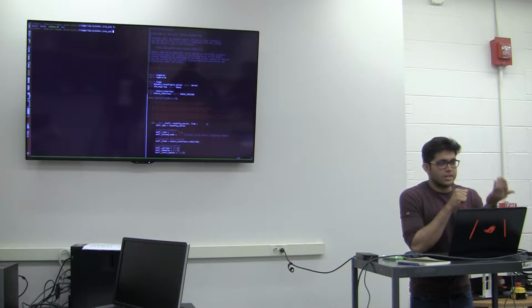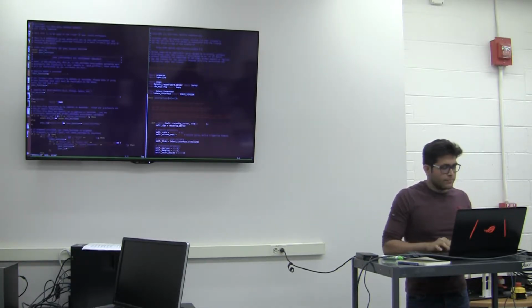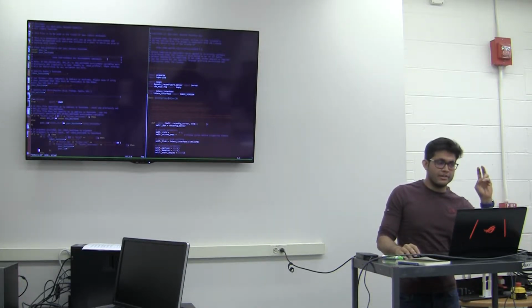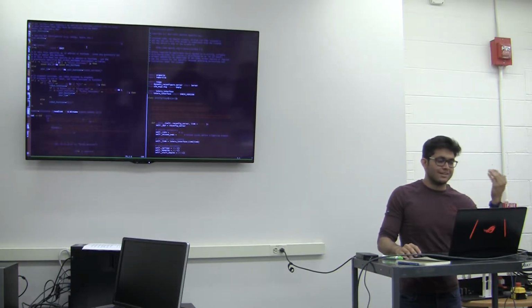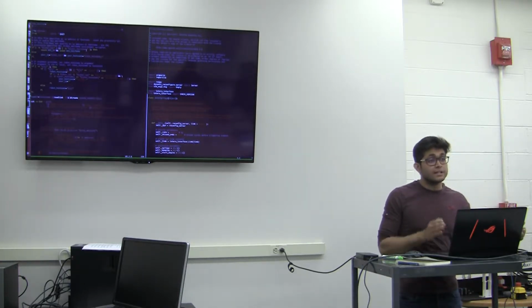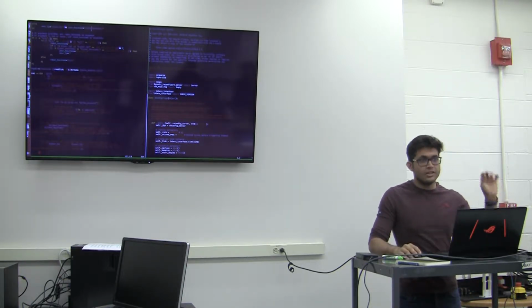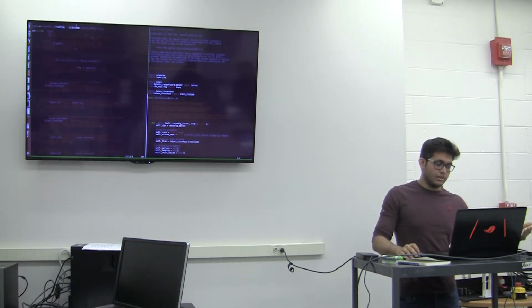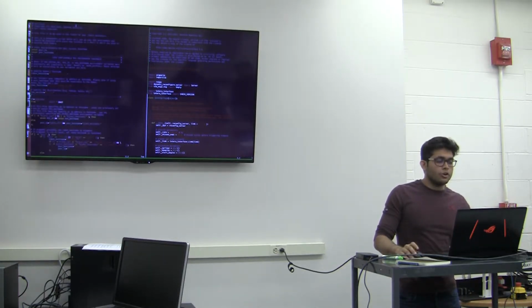So what does intera.sh do? Let's see. You can see intera.sh is taking your host IP address or your host name. It's taking the robot host name and starting the communication. It sets up all your communication parameters. It sources the ROS workspace repository to your bashrc file when you run this intera.sh, right? So the idea behind intera.sh is once you run it, your configuration is done.